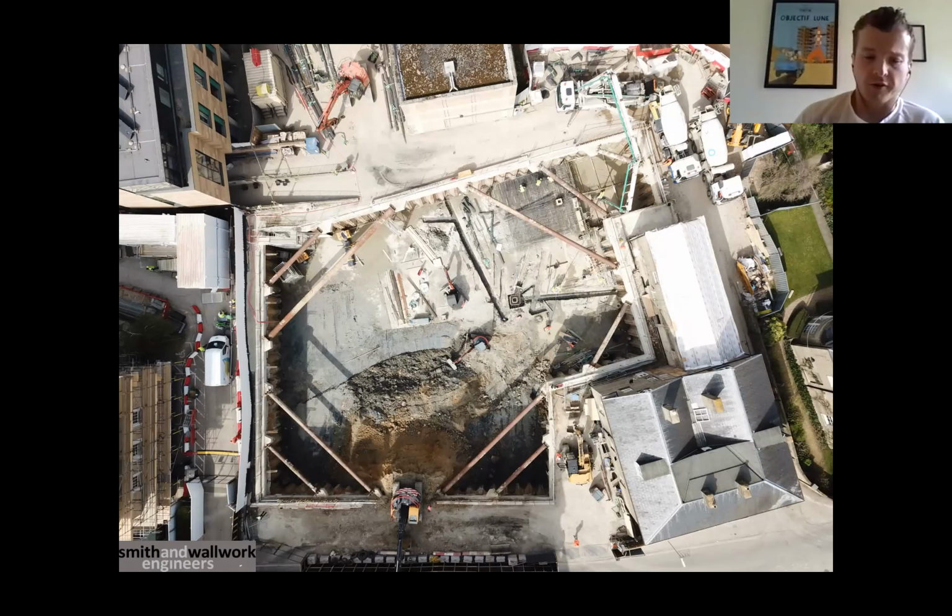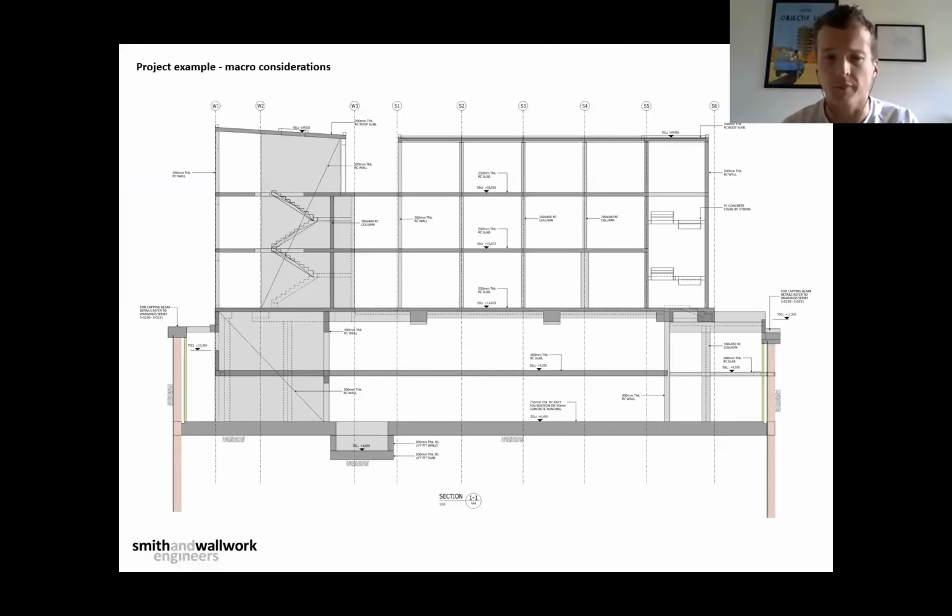And the approach with the basement was very much, how can we build this basement with the absolute minimum material needed? Obviously, climate crisis, we need to build with less stuff, as well as looking at the embodied carbon of it. So it's a sheet pile basement, and from talking to Sheet Piling UK, one of the specialist subcontractors who we've done a lot of work with in Cambridge, we think this is getting pretty close to the limit of what you can do with sheet piles with the Gault clay in Cambridge. So that's good, working at the limit, nice efficient structure.